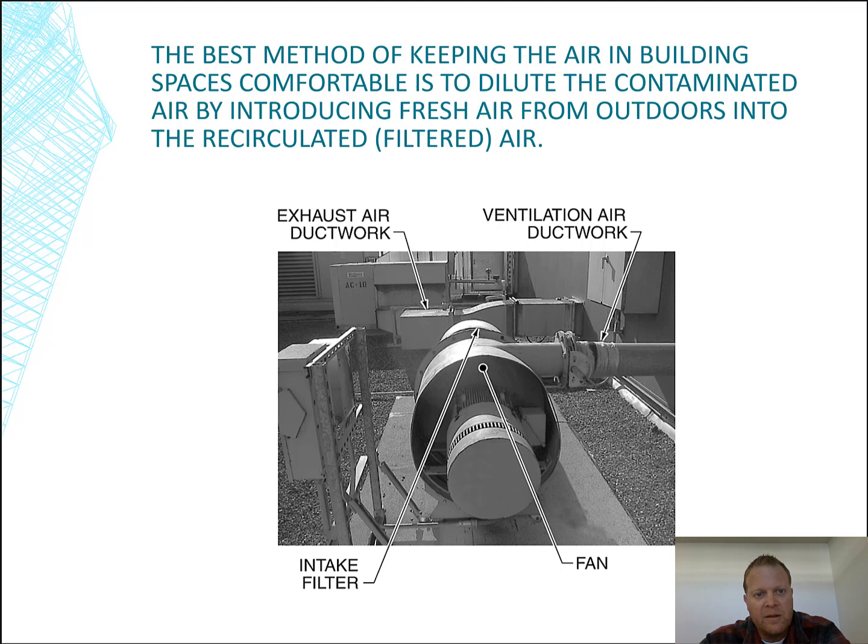There's another way to try and reduce, I don't know if you want to call it particulates, but it would be odors. The idea behind odor removal is to put filtered air into the space and exhaust the air that has odor. In a typical bathroom or restroom environment, I think that's an easy place to understand, they have an exhaust fan, and that exhaust is just pulling air out of the space and dumping it outside. It's a pretty simple system, right?